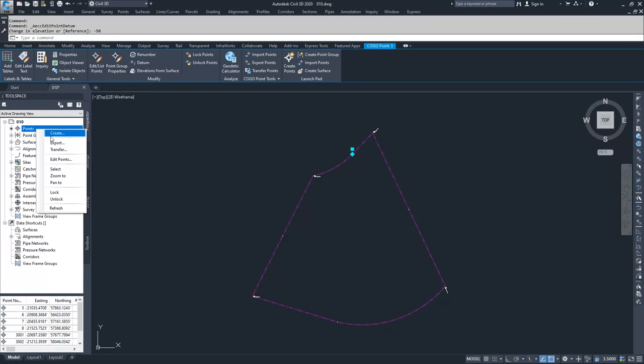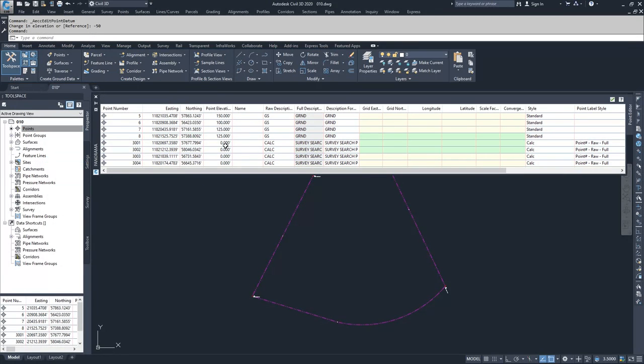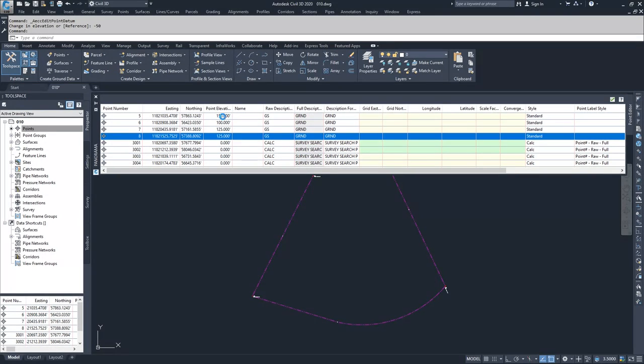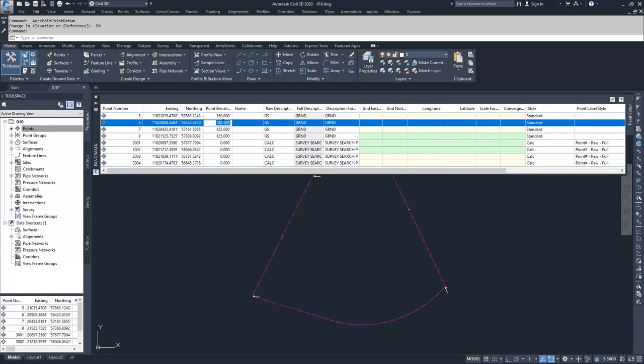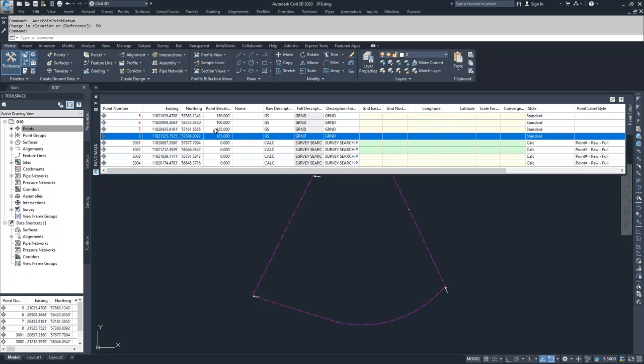And what you'll see is that all the points dropped back down by 50 feet. And you could adjust each of these points individually by selecting them and adding 50 feet to them. The other thing that you can do while you're inside of this Panorama window for editing points is adjust your easting and northing of the points that you've selected. Say you had a point readout of what a specific location was and what elevation it was, then you could change those eastings and northings and choose an elevation based on that point readout, and then it would modify it in the drawing down here.